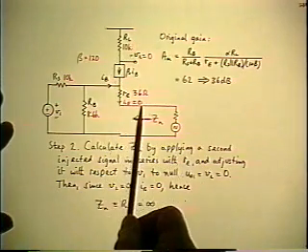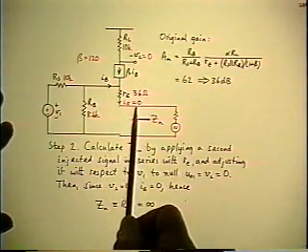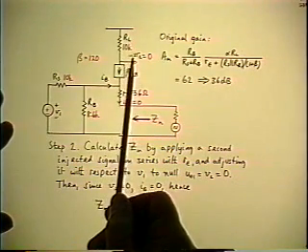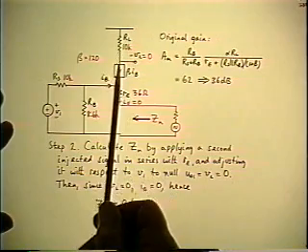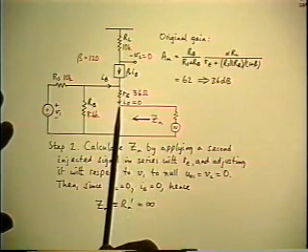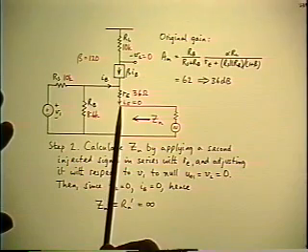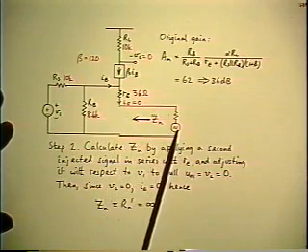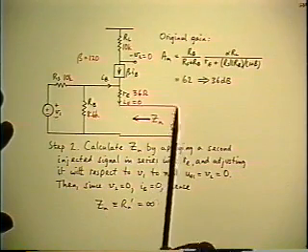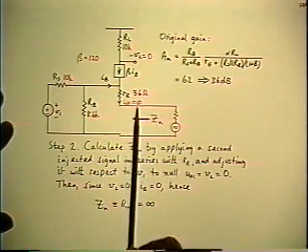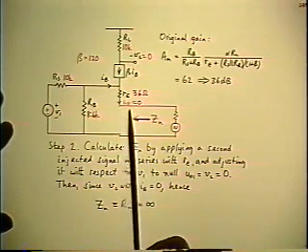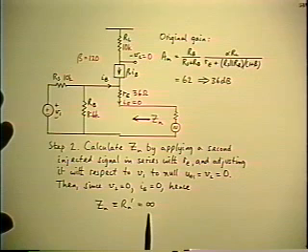Propagate the null back to the second source and see what happens to the current. So the argument is exactly the same as before. If V2 is 0, you have 0 current in RL, you have 0 collector current, and you have 0 emitter current. And this time, the emitter current is the only current that goes through the second source. So the conclusion is that regardless of the voltage applied by the second source, 0 current is drawn from it, therefore the driving point impedance is infinite.